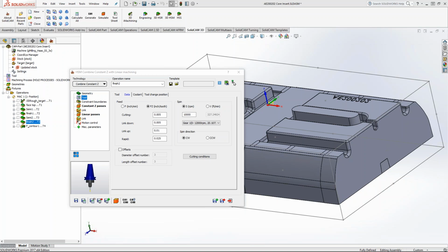I've tried leaving more material. The harder the material, the more it has to cut, the more the tool is going to flex. So keep those things in mind when you're trying to decide how much stock to leave. Your step size is going to probably remain the same. You may vary just a little bit, maybe a few tenths or up to 1 thou, but most of it is going to be how much stock you're taking off.